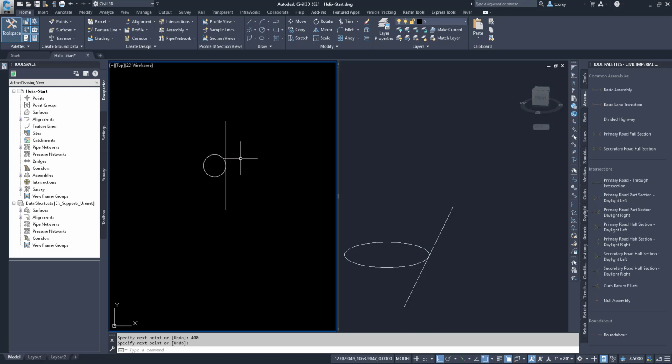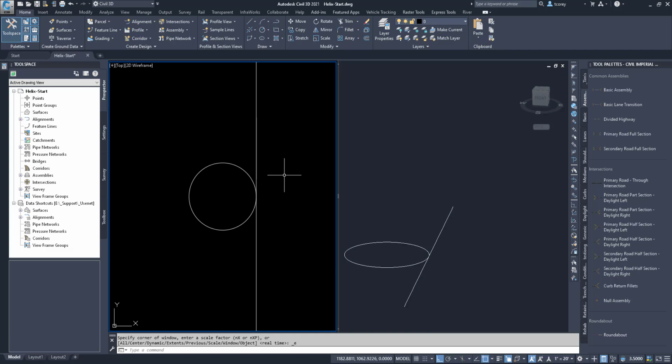All right, so now I'm ready to offset these circles. The reason for this is it gives me clear points that I can select as I'm selecting points along this alignment. And then when I'm done, I'll grab those grips and drag them out where they're actually supposed to be. So I'm going to offset 10 feet this item to that side, this item to this side.